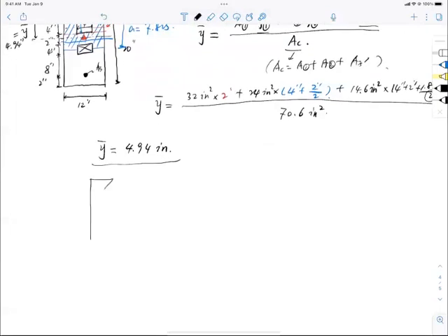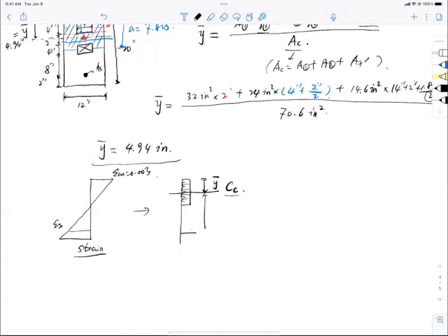It means that if I were to find the strain diagram, I don't even want to look at it because I know it doesn't matter. I have this one equal to 0.033 anyway, and I want to look at my stress distribution diagram. Now y bar is the distance between the total compression and the top surface. If this is where the steel is, and this is AsFy, now the lever arm jd should equal to ds. By the way, this is ds, the depth. So ds minus y bar.